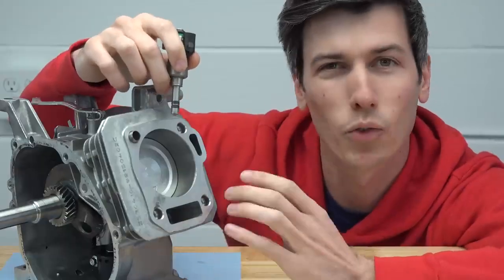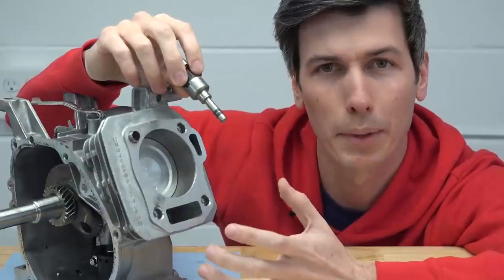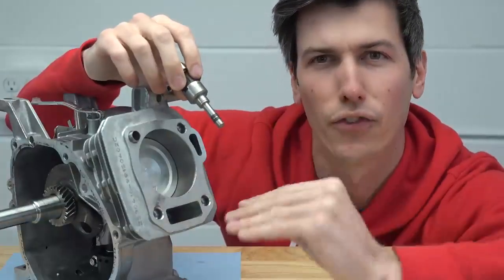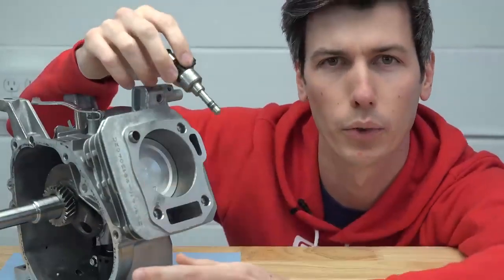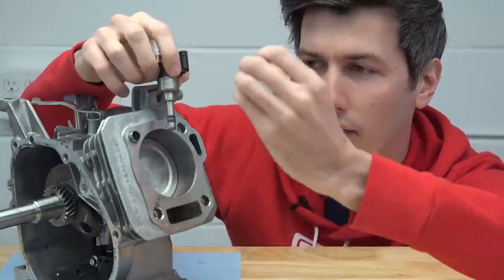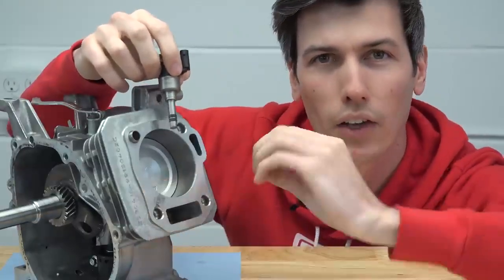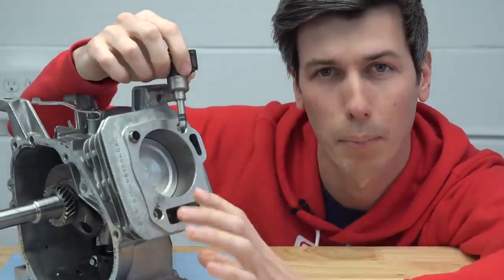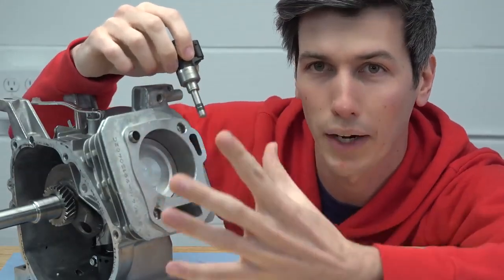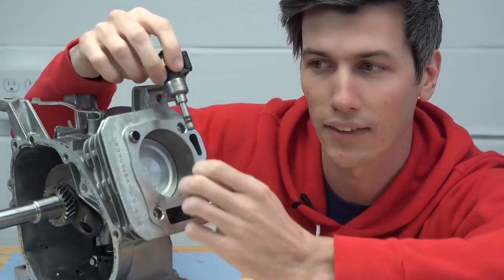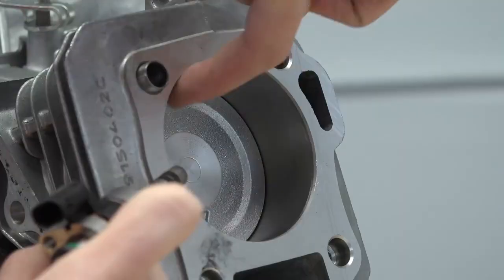So there's a couple reasons why you want to use those higher pressures with direct injection. First being that you want to have that mist as fine as possible. With a port injection engine, there's plenty of time for that air and fuel to mix. With direct injection, it's going right in during the intake stroke, so you've got less time for that air and fuel to mix. So you want it to be sprayed out as fine as possible so that it mixes as quickly as possible. You also want to spread it out as much as possible within that cylinder. So by using really high pressures, you can spread that fuel out nicely throughout the cylinder.